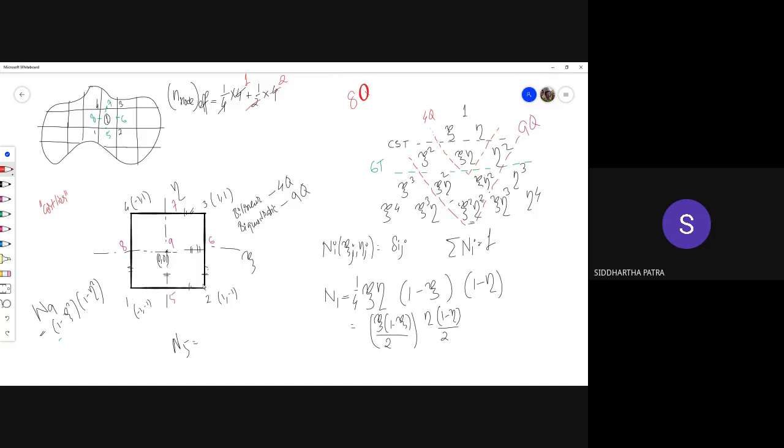But let's say there is something like an 8-noded quad element, and we can do a direct math that 8 nodes is twice that of 4 nodes. But when it comes to sharing, the corner nodes are more shared than the mid-side nodes, and effectively the node count, instead of becoming twice, becomes thrice.